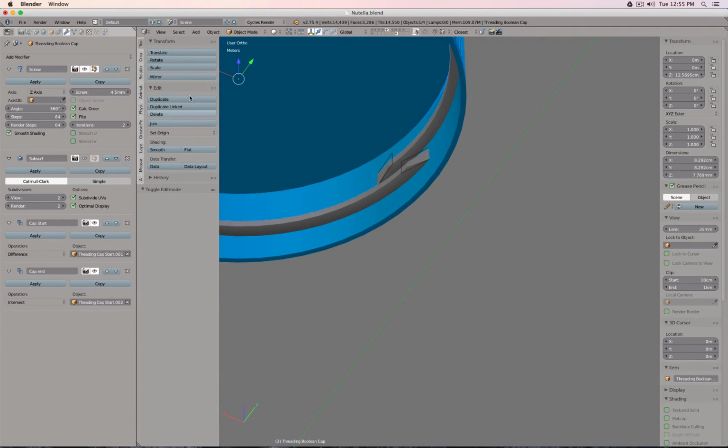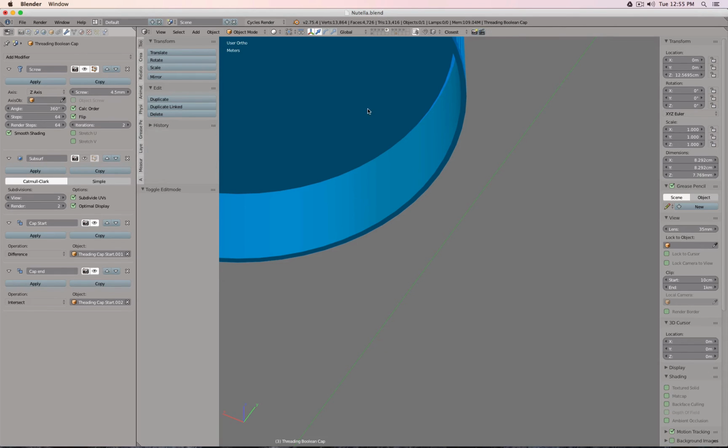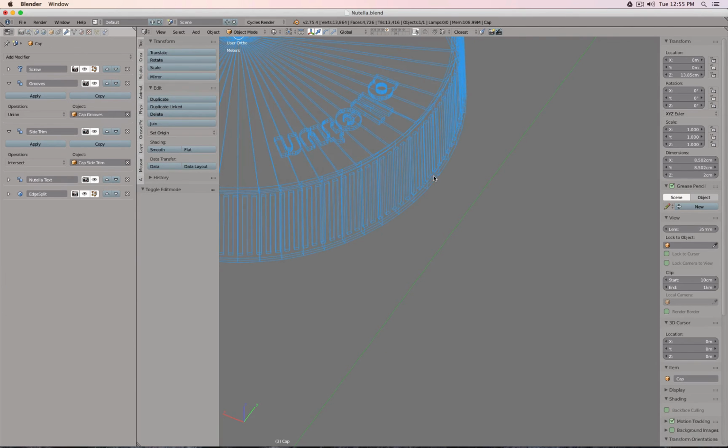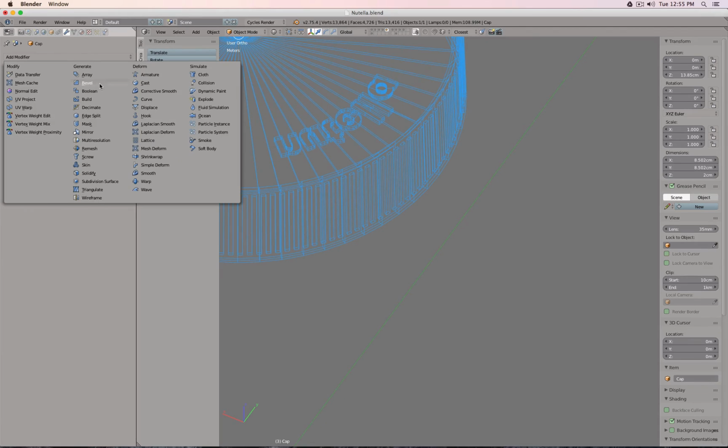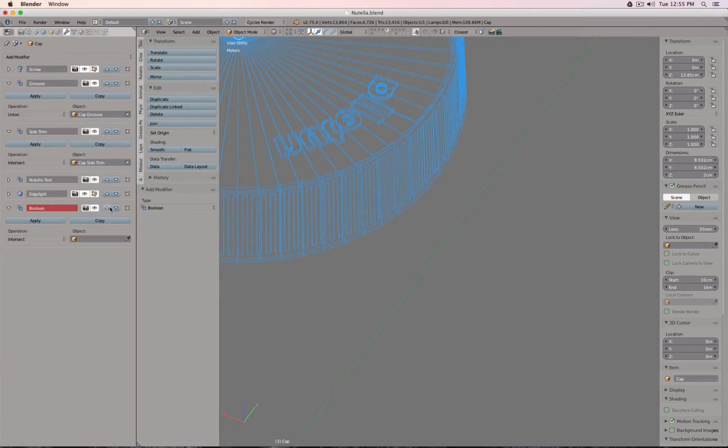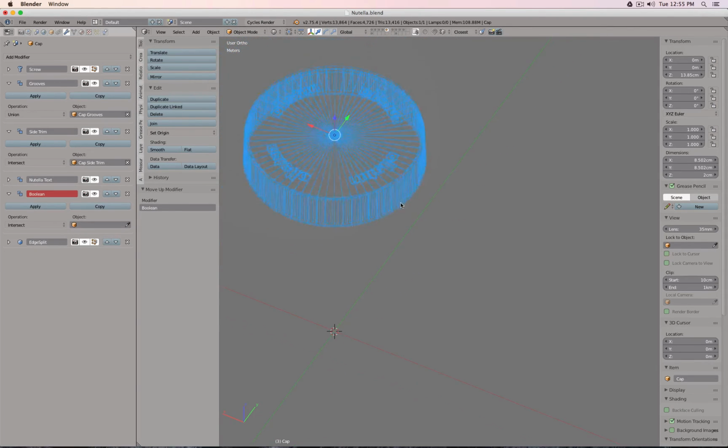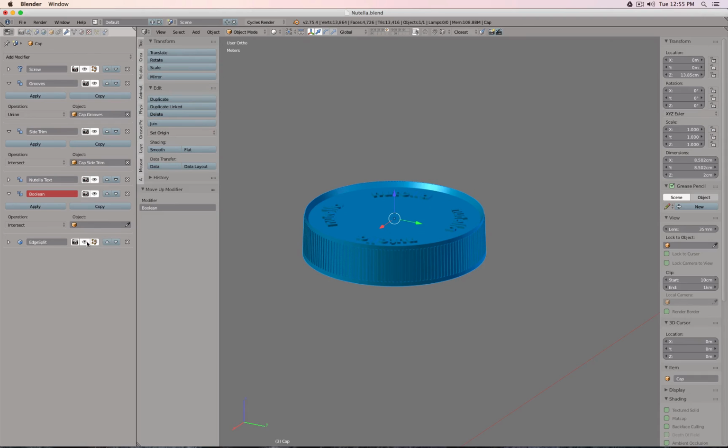Okay, good. So now with this fixed, we can go to Boolean, put this in front of the edge split. This always should be the last, because this always cuts edges for me, it breaks them. But if edges are broken, then basically the surface is open and then the Boolean modifier will fail, which is why it should always be in front.